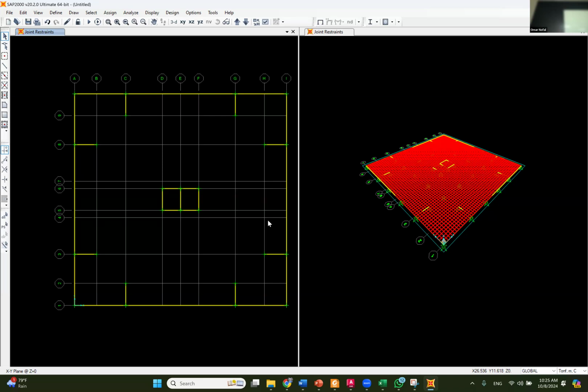This stiff element is a shear wall, but I didn't model it as a shear wall; I put an equivalent beam that is very stiff. Like, the height of this beam, for example, is 0.7. If I multiply the inertia by 10, that means we replaced it with a beam section that has a very big depth. Let's see the difference. I'm gonna show you right now.